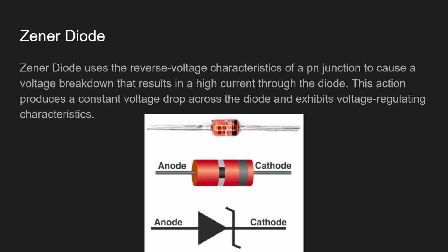Just like in lesson 3 I've told you, everything can conduct electricity. The matter is just how much voltage we have applied, right? Okay, remember that Zener diode is special. You have to connect it in reverse bias, reverse voltage characteristic, okay?